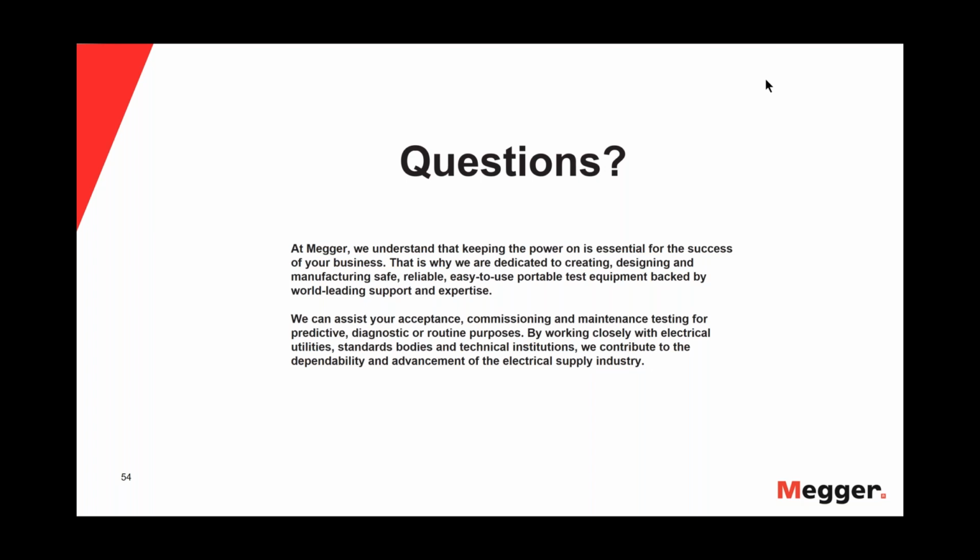Thank you, Robert. Henning, if the megohm test is 100 megohms or greater, how do you proceed? Well, if the megohm reading is high, 100 megohms is a pretty good reading, so it would suggest that it's a good cable.